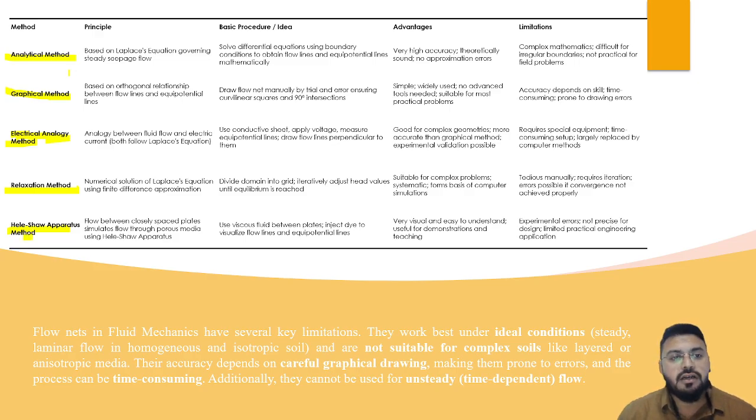So the analytical method is based on the Laplace equation governing steady seepage flow. The basic idea is solving differential equations using boundary conditions to obtain flow lines and equipotential lines mathematically. Accuracy: very high accuracy. Theoretically sound, no approximation errors. Limitations: very complex mathematics, difficult for irregular boundaries, and not practical for field problems.